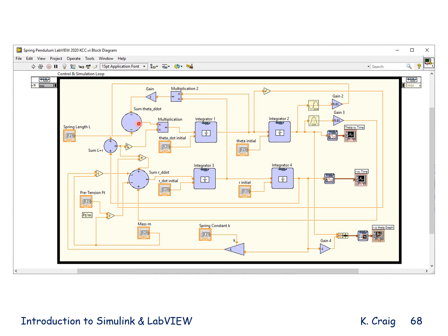Times the sum of minus 2 times the product of this line here, theta dot, and this line here, R dot. Then minus, and I follow this line around, minus 9.81, which is the acceleration due to gravity, times the sine of theta in radians. This is g sine theta. That is my first equation.